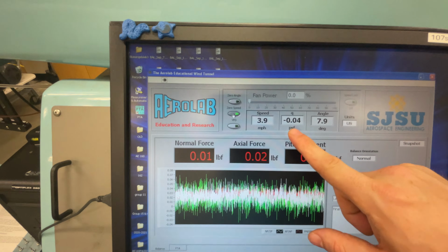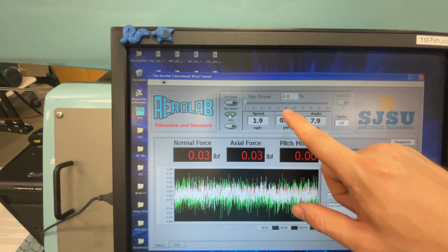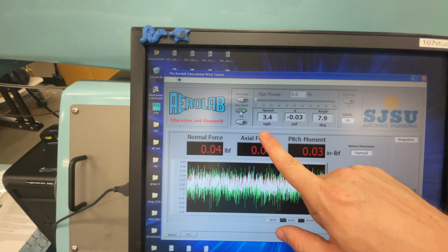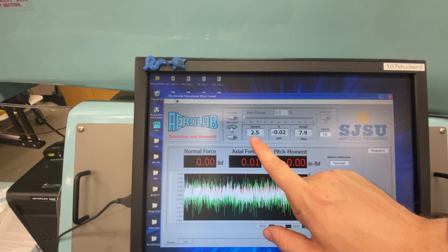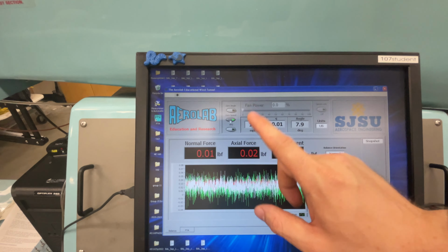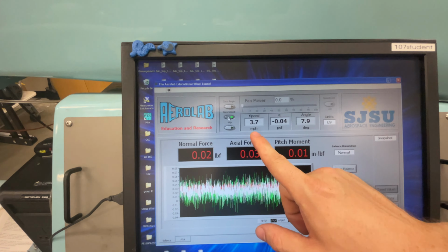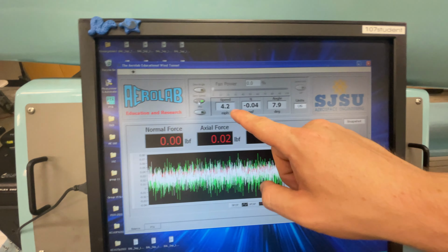One thing to, again, like I said, it's measuring Q. It is using Q, dynamic pressure, to calculate velocity, right? Q equals 1/2 rho v squared. The issue with this is it's also making an assumption about what the density is. I'm not exactly sure which value they're using. You could do the math and figure it out, but they're using probably a fairly standard sea level density for this calculation.